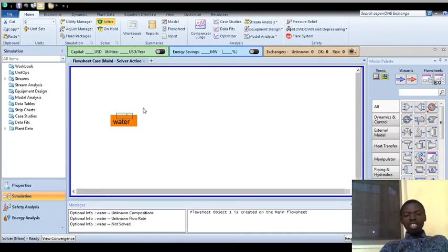Are you with me? Now, if you are dealing with water, can someone tell me what the vapour fraction condition will be without me putting it? It will be 1, isn't it? Because you are dealing with only water. So you go to composition and add it, which is 1. Enter. And then you click OK. Go back to your conditions.